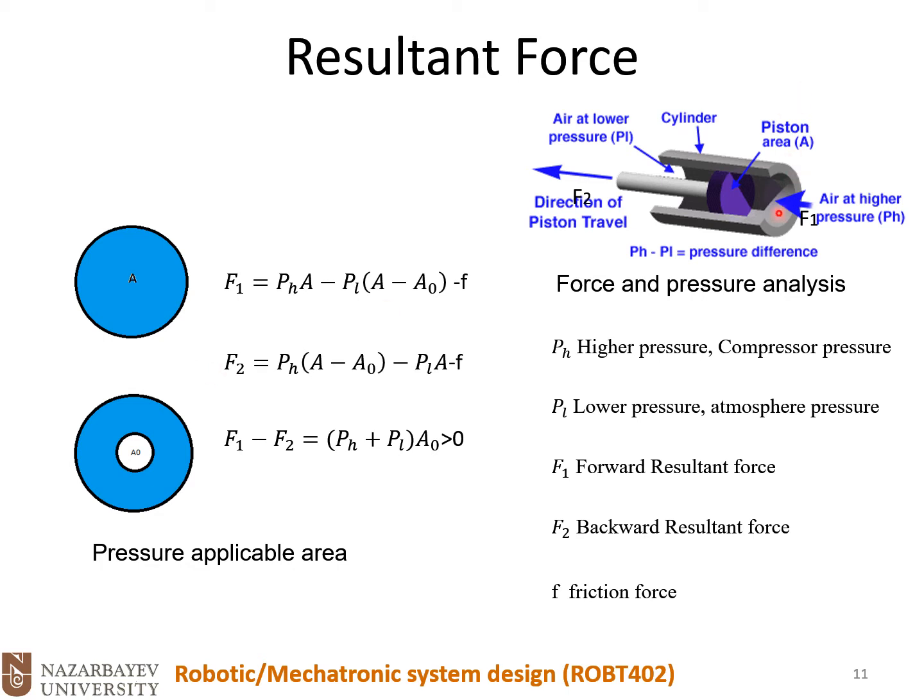Now, let's do the opposite, so let's say we want to move the piston backward. We need to pressurize the left chamber and depressurize the other one.